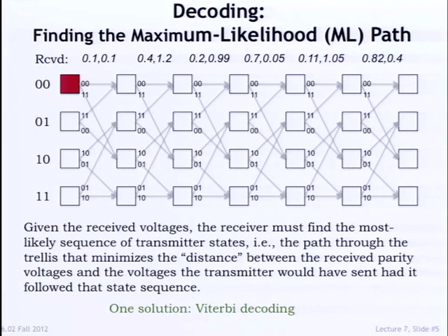So what are we going to do now? Of all the paths available to us, we're going to try and find the path along which the emitted parity bits come closest in some sense to the sequence of samples here, right? That's how, if you were doing minimum distance in some sense, that's what you'd want to do. If you believed that errors further away from 0 are less likely than errors close to 0, then you would want to have a reconstructed set of parity bits along whatever path you choose to come close to the values there.